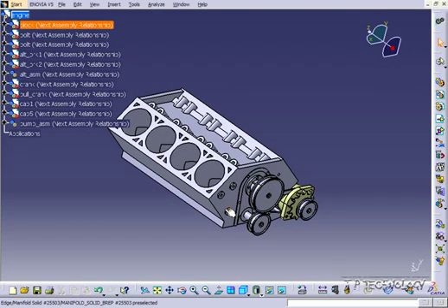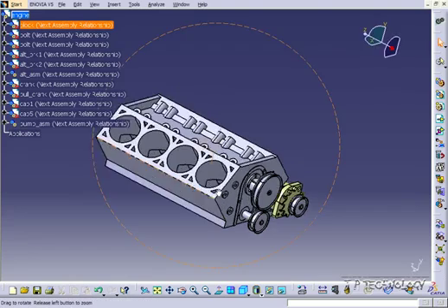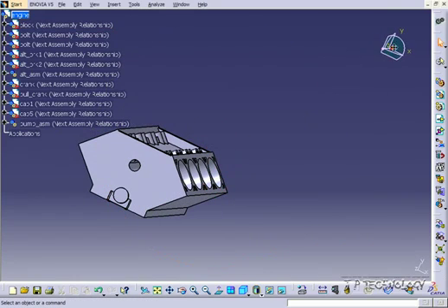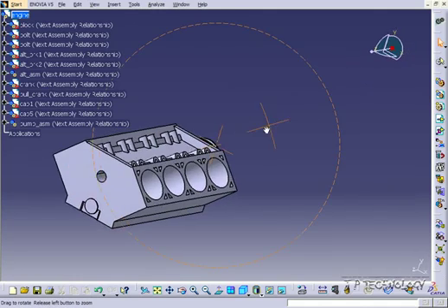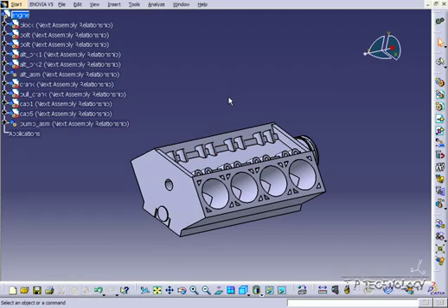And again, I can't emphasize enough how important this is, because if I didn't have an axis there, when you try to throw it in there, you're going to get different results every time. To be precise and consistent every time, create the axis that you want to rotate about. You can use an edge too, but if you want to rotate through, say, a circle, get that center circle's axis in there and rotate about that.